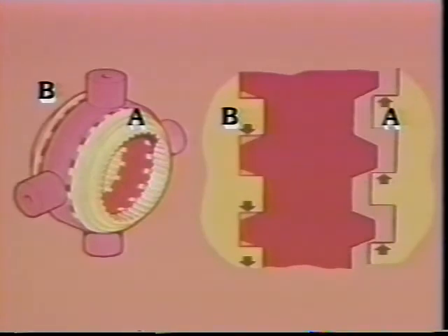Now here's how the no-spin differential works. If clutch member A is pushed faster than clutch member B, A's inner row of teeth will try and push the center cam along with it. B's inner row of teeth prevents the center cam from moving. Clutch member A finds it easier to push back the return spring and slide up the sloped teeth of the center cam than it is to push the center cam ahead.